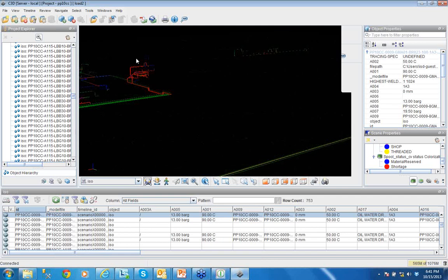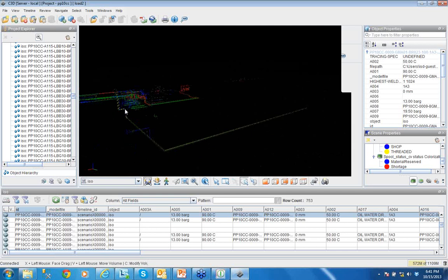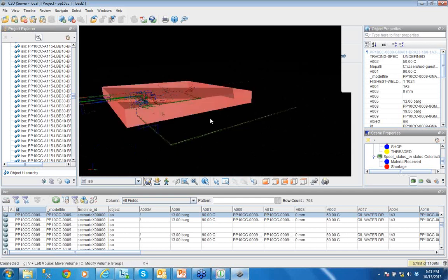Okay, thank you, Chehade. There's one item I need to add, just for this specific requirement. There is a capability within this system which we call the volumetric approach. Now I'm going to draw just a small volume. And with this volume, I can ask the system, take the content or whatever is inside this volume, whether loaded or not, and make a model out of it. So in this case, even if there is some hardware limitation, you can still use this approach to splice your model into smaller pieces, and you can load it.